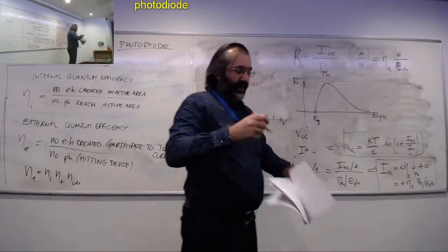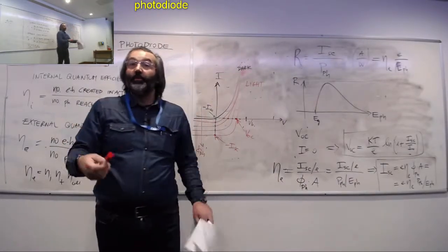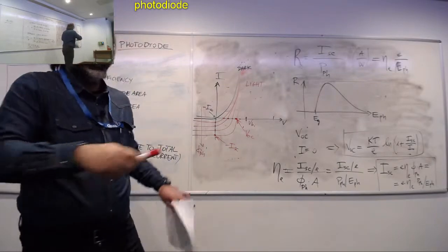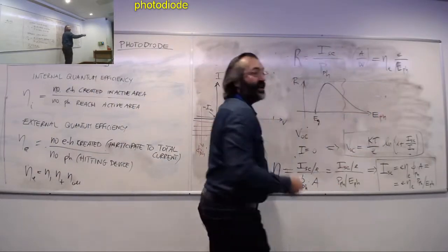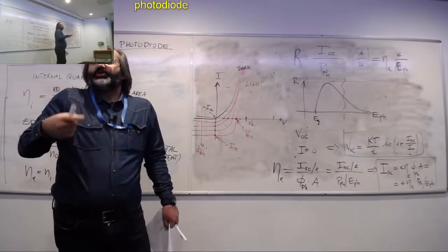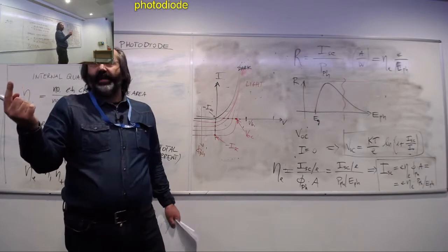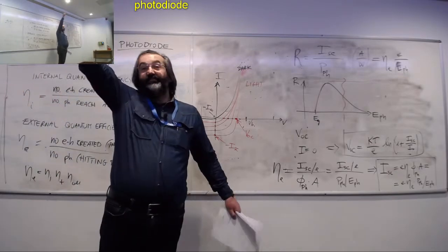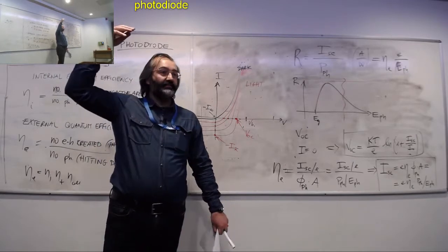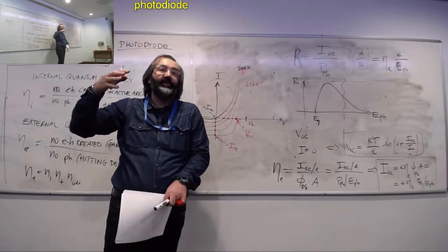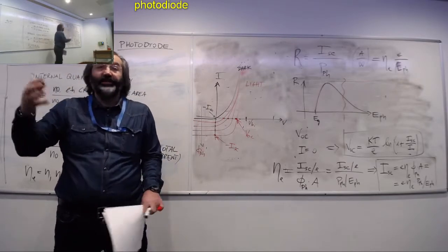The idea here is that when you start exciting the semiconductor with very energetic photons, so in this region, for example, those are not used efficiently. They still create just one electron-hole pair. They are excited very high in the conduction band or the valence band, but this energy then is lost through thermalization. So there is a lot of heat also being generated through these processes.